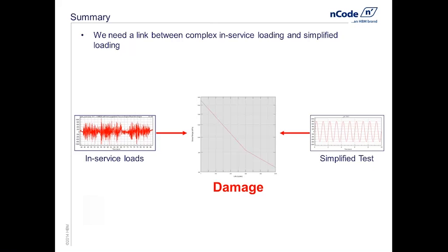And then we also use GlyphWorks to help us define the important parameters of our test spec. So that important parameter was the amplitude. You remember we chose that amplitude. We also then used GlyphWorks to calculate the number of those amplitudes required to reach this common link, to make those two damages equal to each other, thus ensuring that we have an apples-to-apples comparison.